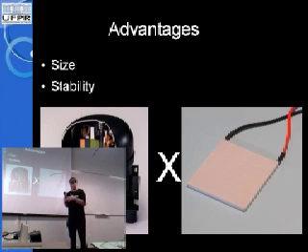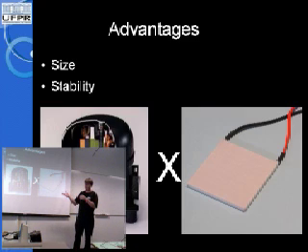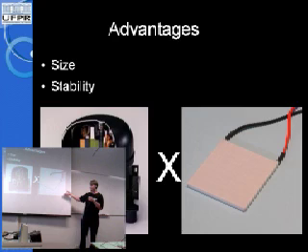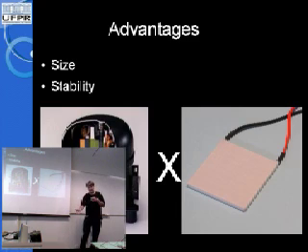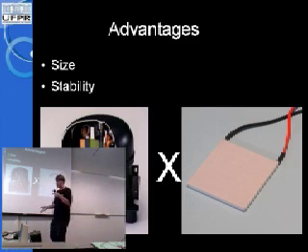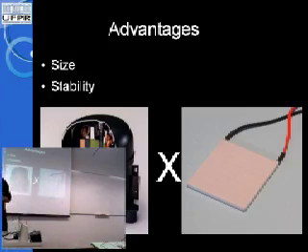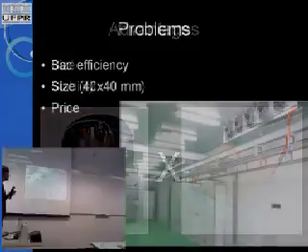So there is this problem on the conventional coolers. We do not have this problem on thermoelectric coolers because it's simply N-type and P-type silicon, no vibration, only current passing through it and heat passing from this side to this side. So it could be good, but there are problems.